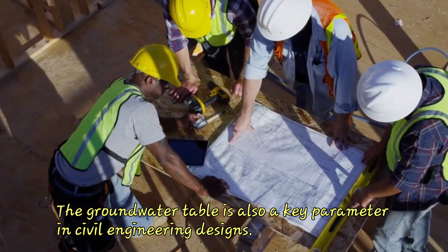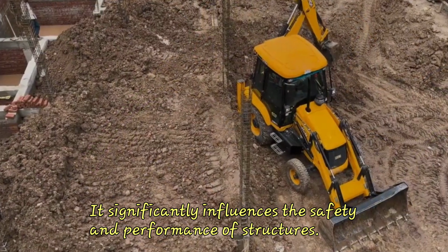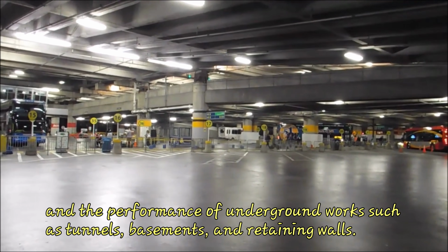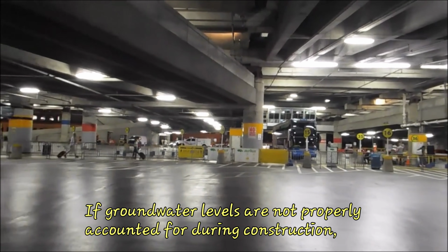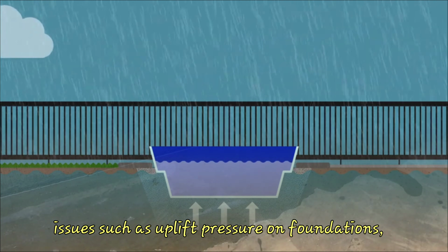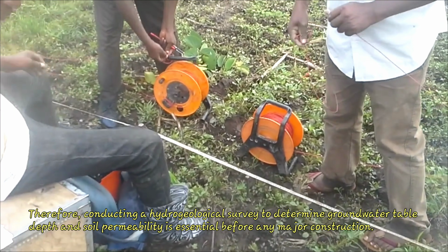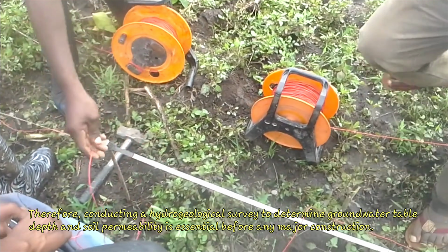Groundwater table is also a key parameter in civil engineering designs. It significantly influences the safety and performance of structures. The level and behavior of groundwater can impact soil stability, foundation design, and the performance of underground works such as tunnels, basements, and retaining walls. If groundwater levels are not properly accounted for during construction, issues such as uplift pressure on foundations, seepage and leakage, soil instability or heaving, and even structural failure can occur. Therefore, conducting a hydrogeological survey to determine groundwater table depth and soil permeability is essential before any major construction.